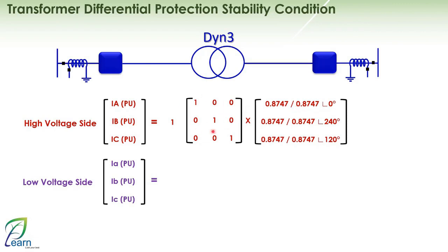And what number does it multiply in the matrix? In the matrix it's number 0, and therefore the total result will be 1 over 3 phases at an angle of 0, 240, 120. So what is the unit of measurement here? The unit of measurement here is per unit because I have already divided it from the base.